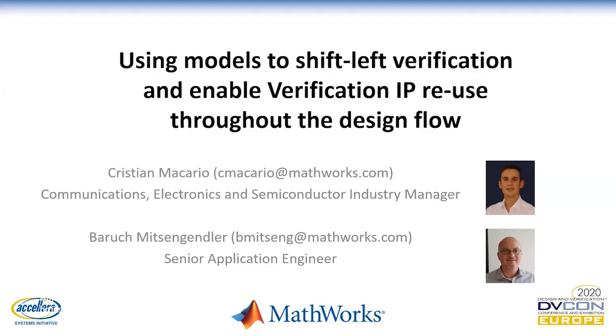When it comes to verification, shifting it left is not enough. We also want to reuse all what we do at system level throughout the entire design flow. So we want to reuse models and test benches that we use at system level also at implementation level, RTL and SPICE, depending on whether we are analog or digital designers. But we might also want to reuse all the stuff we have in post-silicon activities like testing and characterization, for instance, and there are companies doing this. We will see some examples later.